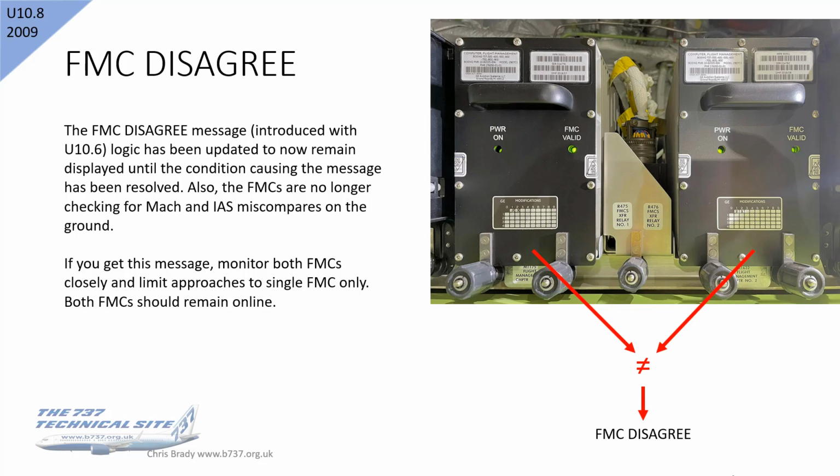If you get this message, standard procedure really, just monitor both FMCs closely, and the strong advice is to limit approaches to single FMC only. Both FMCs should remain online, even with a disagree.